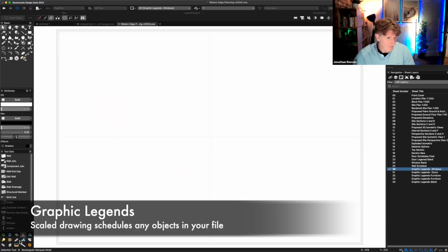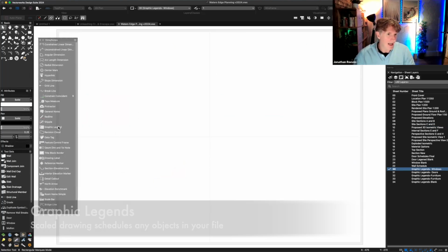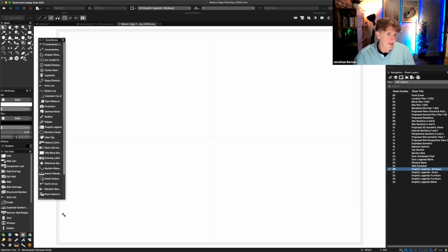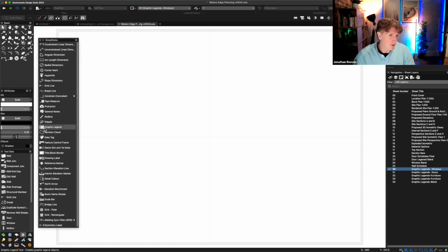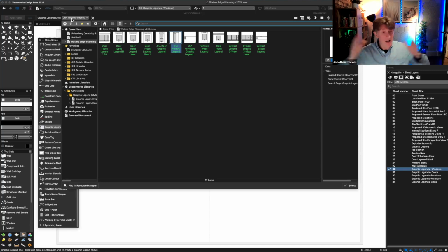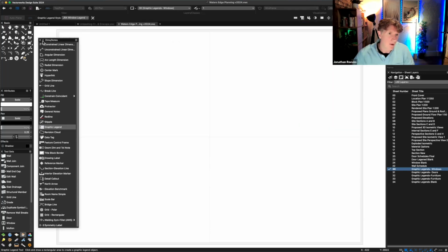So all I would do is go into my Dims and Notes, select the graphic legend tool here, go up to the top, and choose from a library of graphic legends that Vectorworks give you, but also ones I've tweaked and modified and made my own. I've got a library of these. So you can see some of the standard ones here. I think it was that one. So I just double click to activate that one.